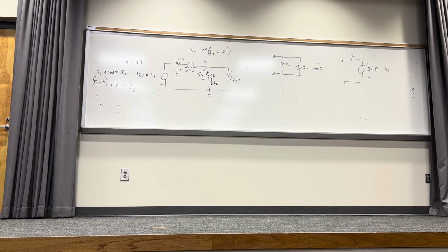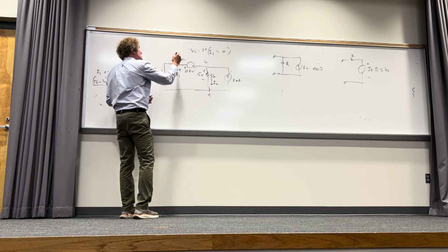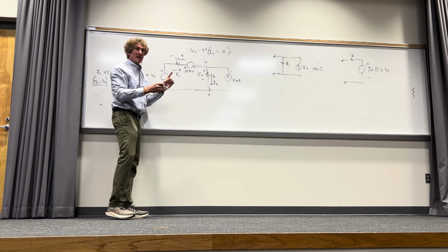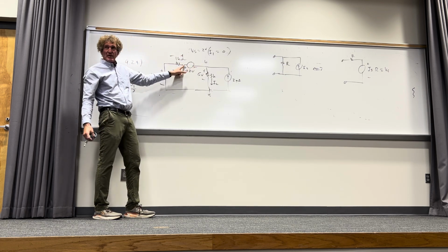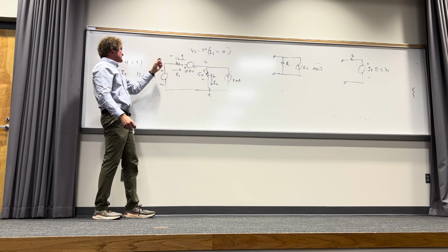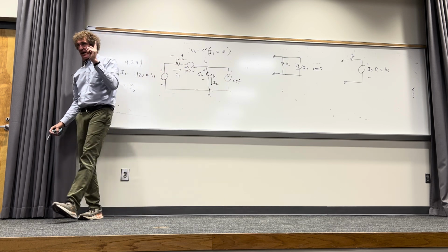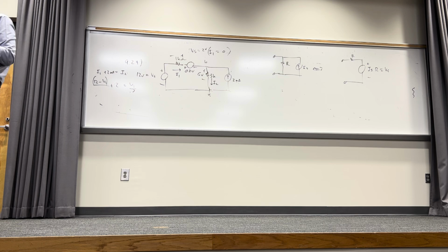You have a troubled look. Do you see it? I want to make sure the V1 plus 0.7 is in parentheses, right? So look, it's the 12 voltage minus across the 1K is what? Well, it's V1 plus 0.7 on that side, and it's VS on that side. So VS minus V1 plus 0.7 over whatever that is, 1K. Agreed? Yeah. Okay. You good with that?